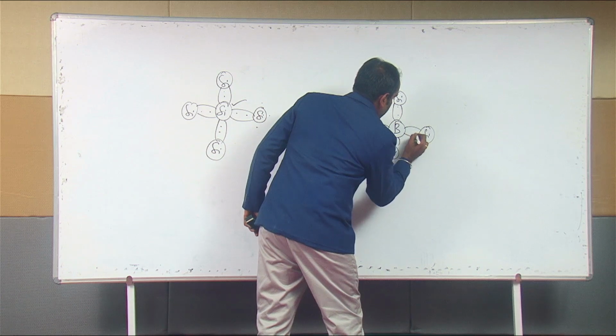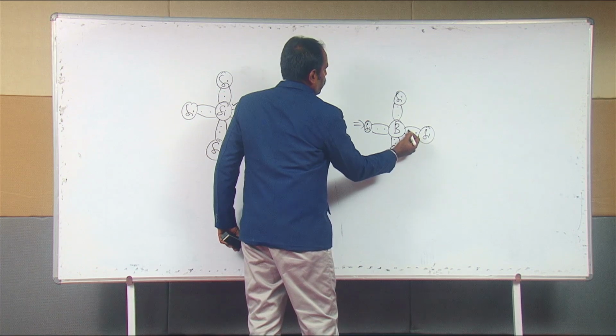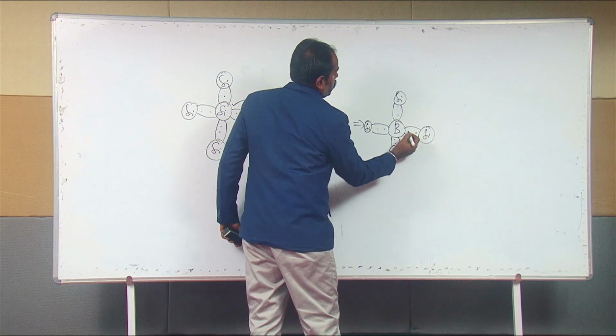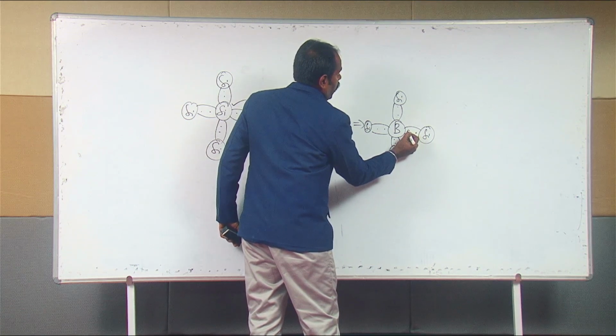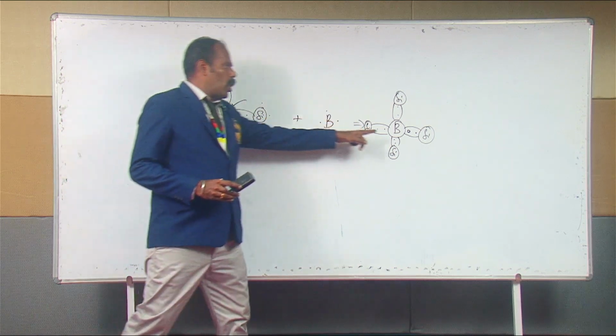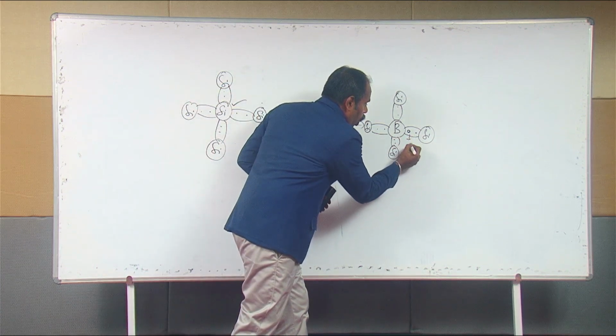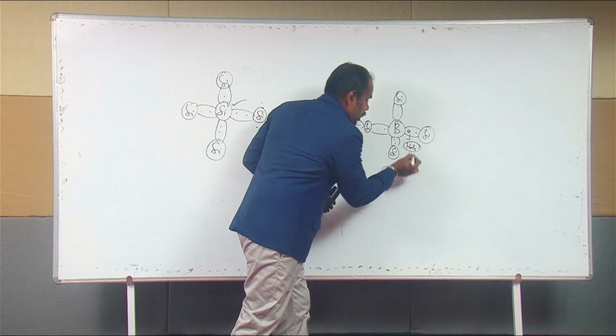But you could see that from this silicon atom, 1 electron is being offered, whereas there is no free electron available for the covalent bond formation over here, which means we have the introduction of a hole in this place. Now, due to the addition of this boron impurity atom, what has been newly introduced into the system? A hole has been newly introduced into the system.